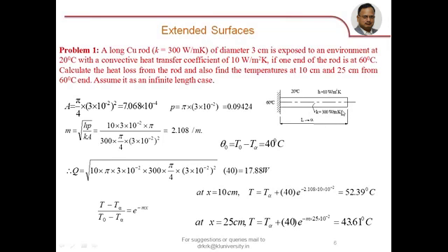If you go for a too long fin, the end portion of the fin may not be able to convect heat properly. So via media we have to see, and that is why we have seen the perfect design is where the value of mL should be not greater than 2.5. That care we have to take.